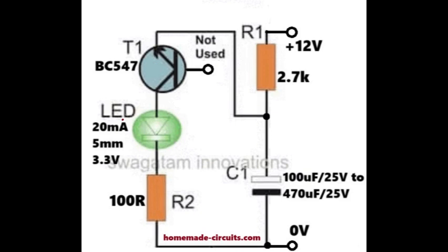As the capacitor's voltage builds, a small displacement current passes through the collector base junction, and that microscopic current slowly raises the internal base potential. When the base emitter junction reaches around 0.6 volts from this internal buildup, the transistor suddenly conducts, like a self-primed trigger. The LED flashes on, drawing current through R2.